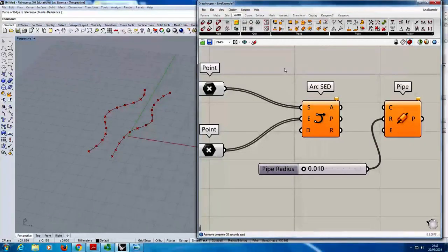So we'll go back to the vector tab. So hopefully you guys are engineers, you know a little bit about vectors already. Vectors are very useful generally, and they're very useful inside Grasshopper as well. So there are different ways that we can set up vectors. Vectors and points inside Rhino and Grasshopper are basically little data structures that hold X, Y, Z coordinates. You can use them interchangeably easily. So components will ask for points or they will ask for vectors, but you can usually plug a point in when it asks for a vector or a vector in when it asks for a point. You can add them together, you can treat them the same.